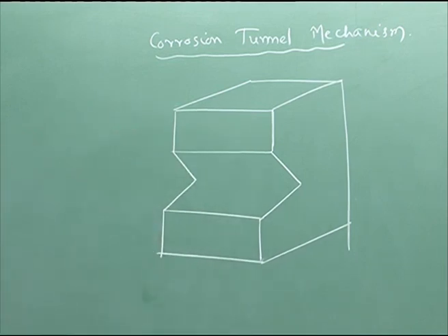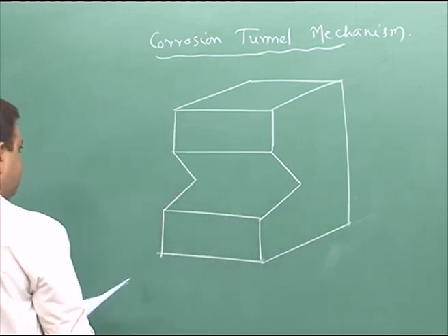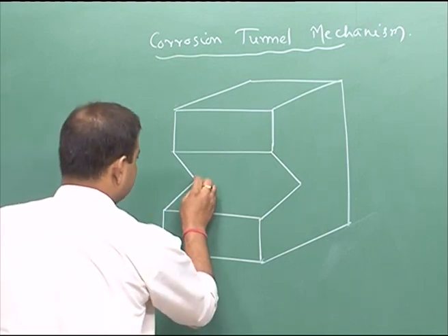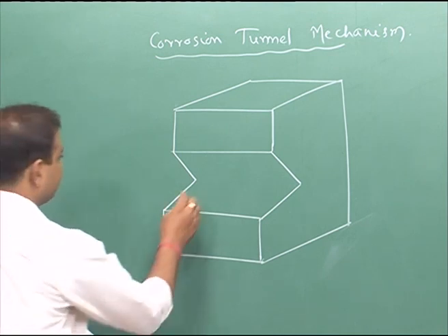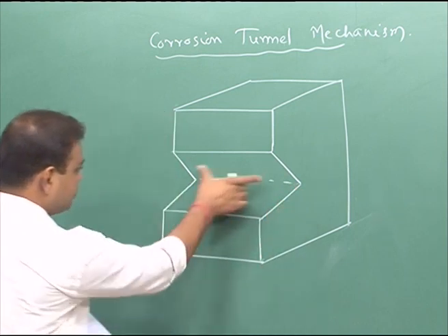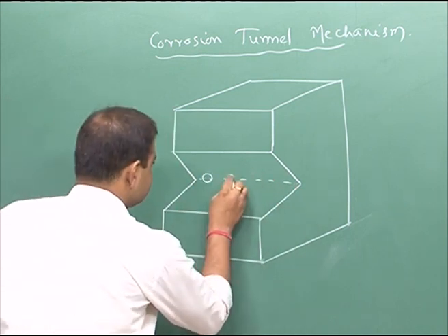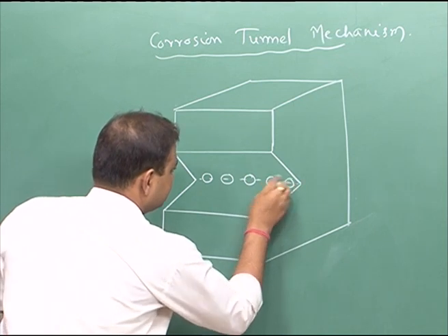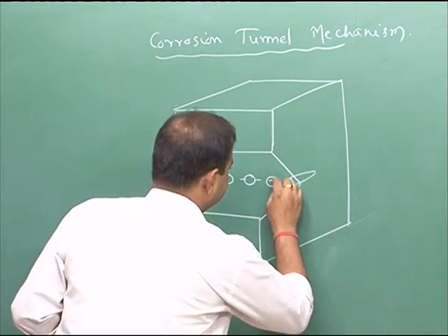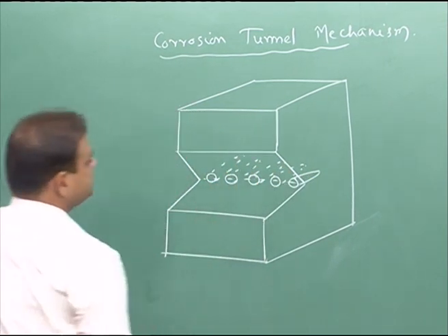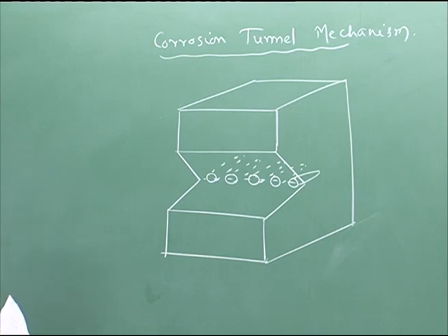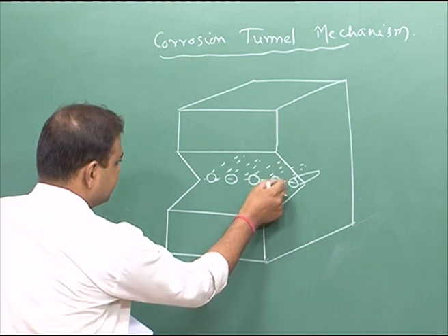if you have a crack like this, that time due to the corrosion effect in the crack tip zone where you have slip steps, multiple tunnels form due to corrosion. This is, let us say, the slip step zone where you have multiple small tunnels, and they are progressing inside the material. These are the tunnels, and gradually those tunnels will grow, and finally, the small ligaments will form.